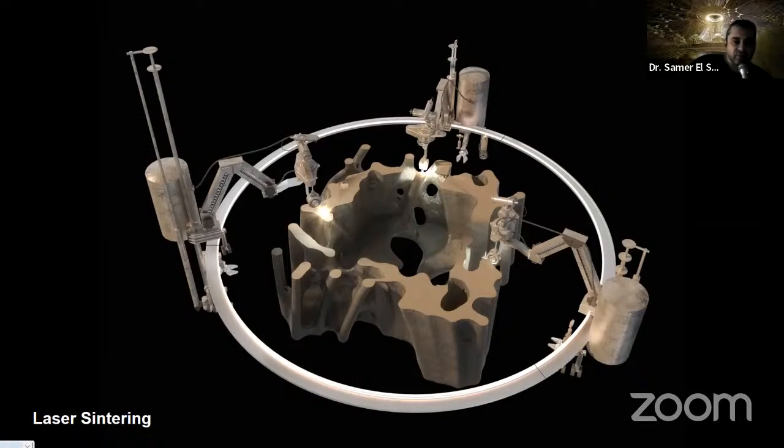One of the techniques is called laser sintering. And we have also laser melting, which is much better than laser sintering. And we have recently solar sintering, which is more sustainable and consumes less power energy in the building process. The solar or laser sintering or even the laser melting are all following the same principle of exerting a very high laser beam energy to fuse the grains of the regolith together.